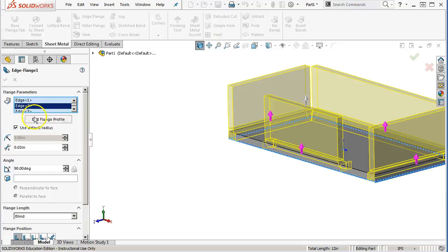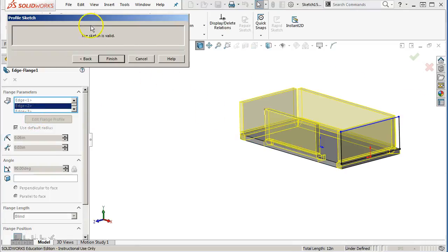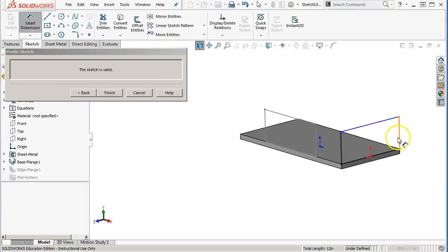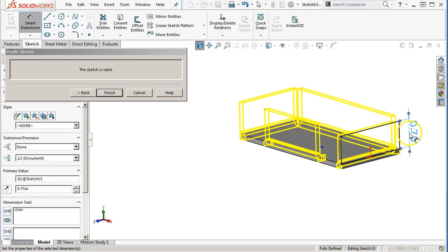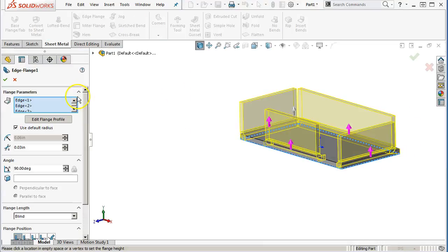All right, so if I go to edge flange 2 and decide that that wall needs to be 0.75, I can adjust it. That one's going to have wires coming out underneath it, or when we put the outside flanges on it to bolt it down, there's going to be some clearance for it to sit over a plate, whatever. Same thing, I grab this bottom point or points, and those are movable.